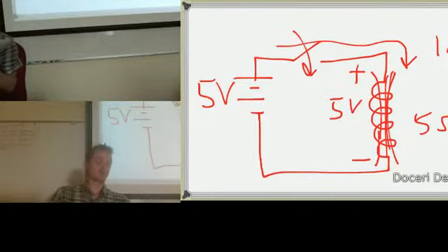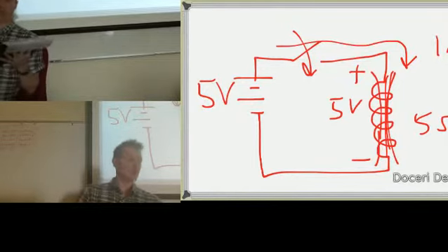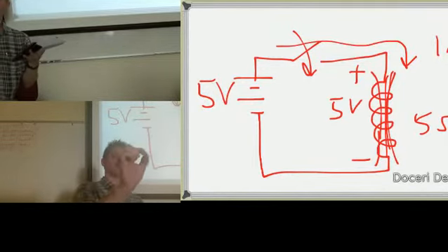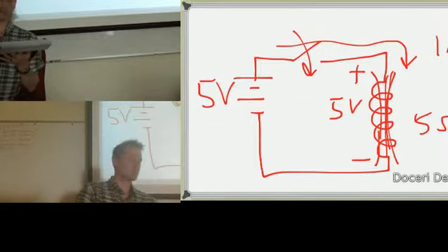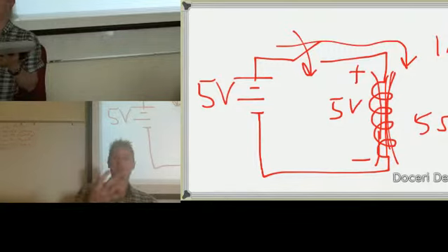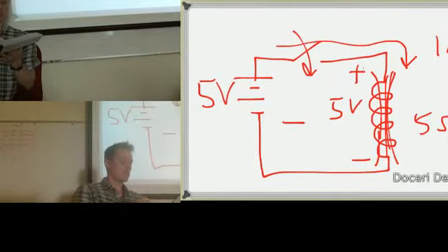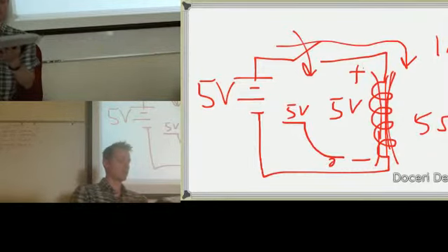Yeah, the initial voltage across this inductor is going to be 5. That means initially, as soon as the switch is connected, there's going to be no current, if you look at the instant that it happens. Because instantly, a magnetic field is going to start trying to build up, but that voltage is going to be induced so as to completely oppose 5. If I have 5 volts here and 5 here, effectively, I have no current, but this 5 volts is slowly going to start to drop off. So 5 volts induced to 0.